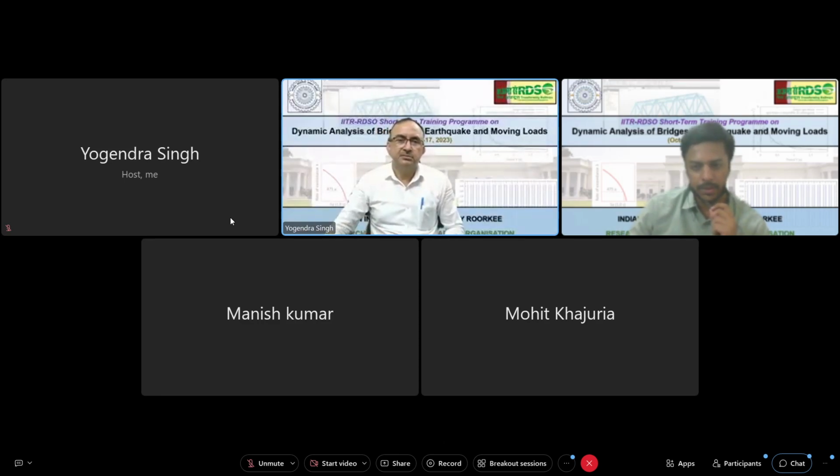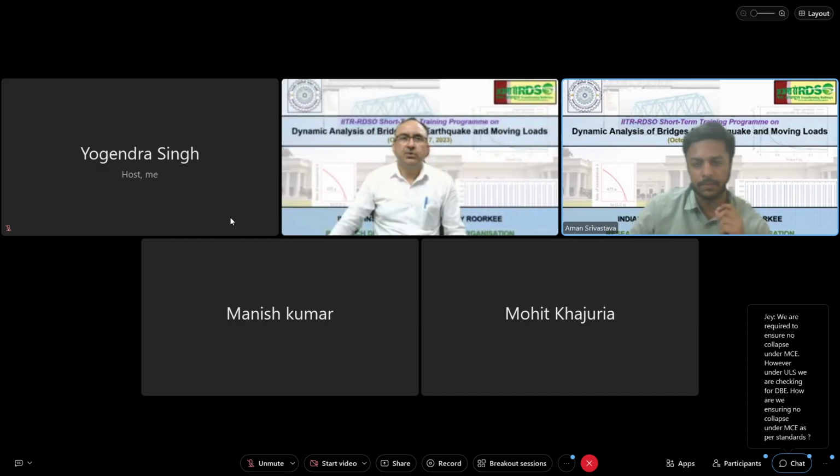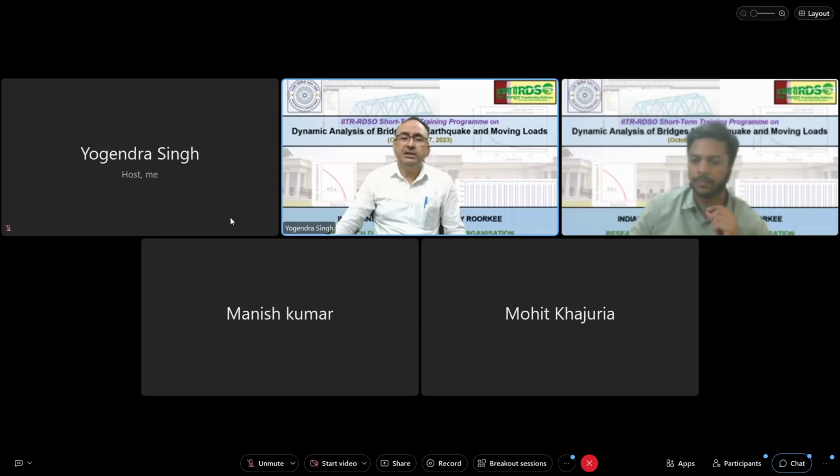Mr. Bush is asking what type of filter we need to require in near fault pulse like ground motion. What type of filter? If I have understood the question, I am not clear whether he is talking about the frequency domain filter or a high pass or low pass type of filter, or he is suggesting that while selecting the ground motions, what filter we should have. So currently, our code is not talking about the pulse type motion. That type of motions are not considered here.